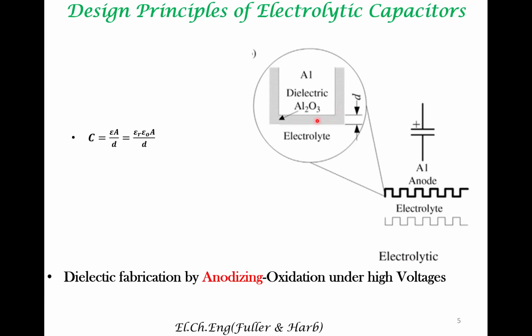As opposed to conventional capacitors, the electrolytic capacitors have a polarity. This anode, that is the electrode wherein there is this metal oxide interface or structure, always has a positive polarity. It is important that you don't connect this structure to this structure.